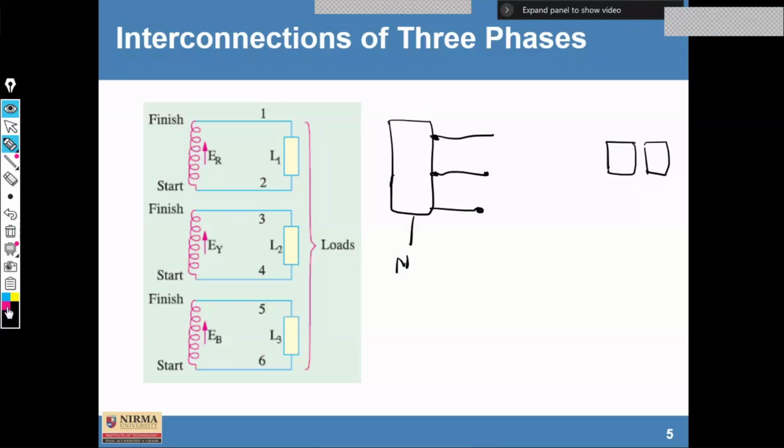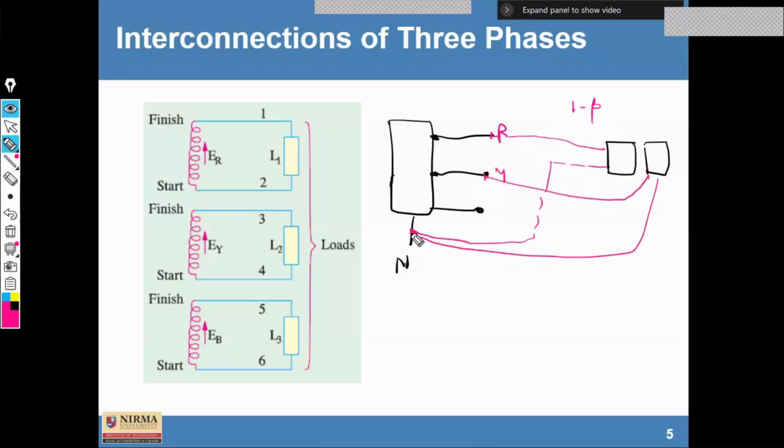So one apartment can use the R phase connection and the return circuit that is provided with this neutral. Yeah. And similarly, we are simply converting into single phase. Right. So this way it is distributed here. Suppose if this one wants, you can connect it to the R phase also, you can connect it to the Y phase also. So an electrician who connects all the different apartments always tries to balance the load here. Right. But somehow the usage is not similar, and because of that there is an unbalanced system.